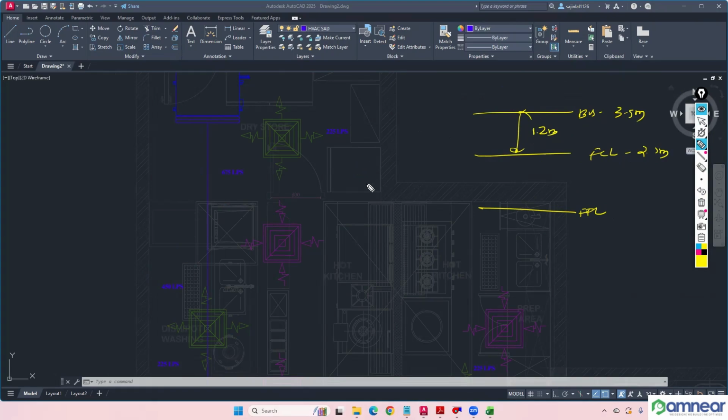As you know, if the false ceiling available is 1200 millimeter, hanging allowance 100, acoustic insulation 50, thermal insulation 50, bottom of duct to the false ceiling 100 mm. So overall, how much you will get? 300 mm.